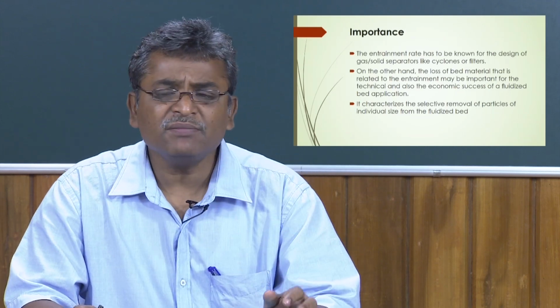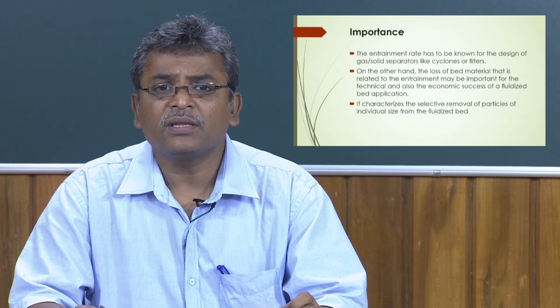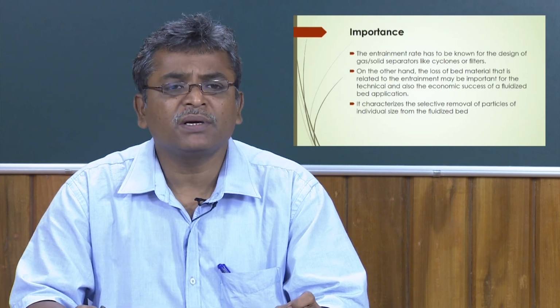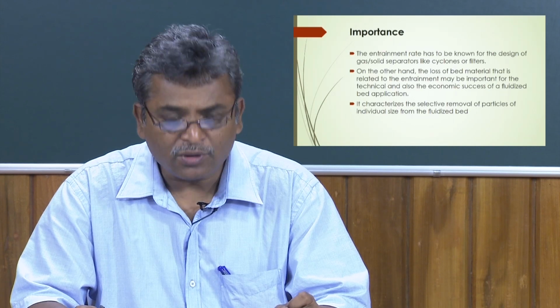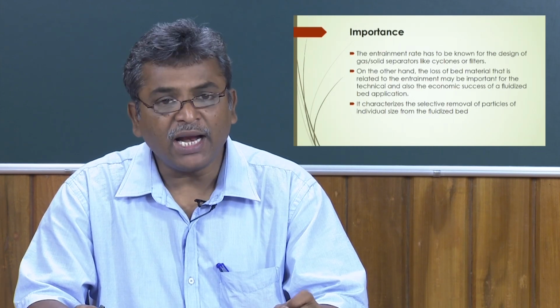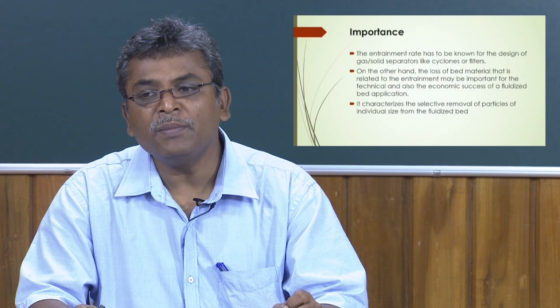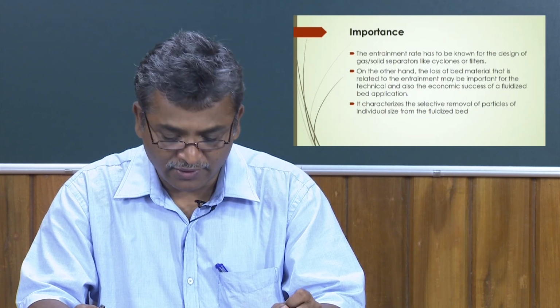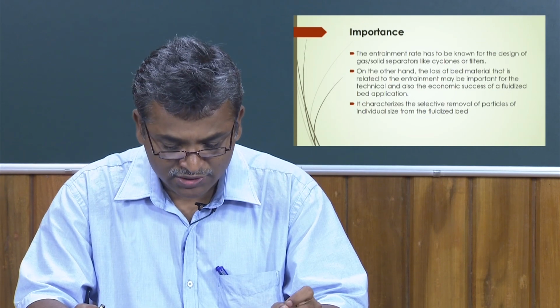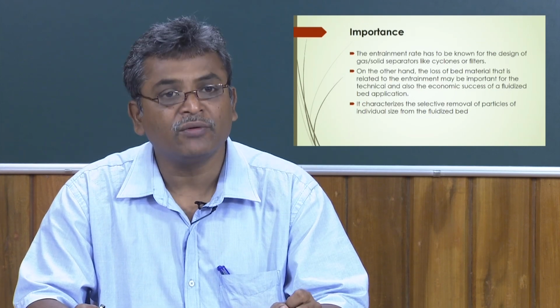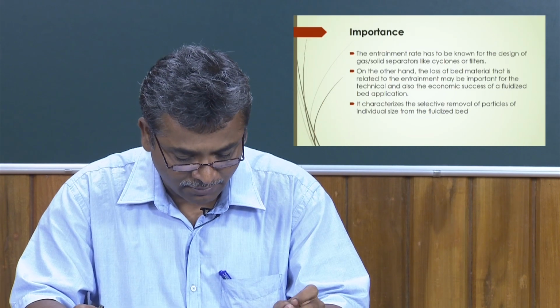Sometimes the internal circulation of these fine particles is required for better transport operation, and in that way the economic operation of the fluidized bed can be achieved by designing while considering the entrainment and elutriation characteristics of the particles inside the bed.